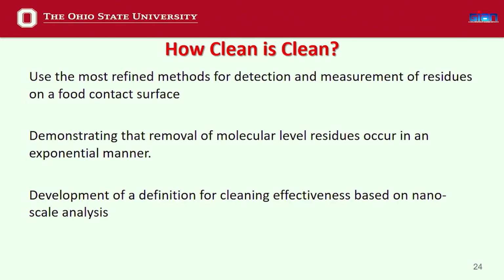So, how clean is clean? For cleaning, you have to look at the molecular level residue that occurs in a certain factor. So, for example, there are some specialized things you can do, like a swab test on the surface being cleaned, and then analyze this with certain quick methods to see how much residue may be there at ppm level or even lower. So, you are able to say okay, this is an acceptable level and so on.